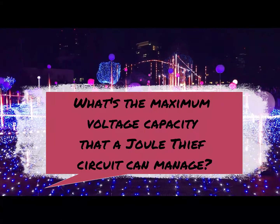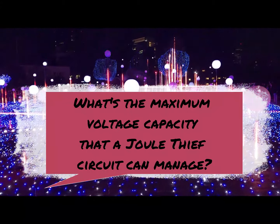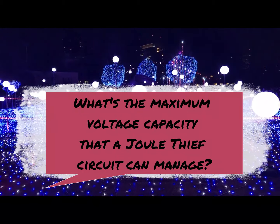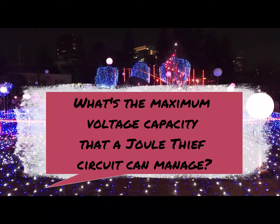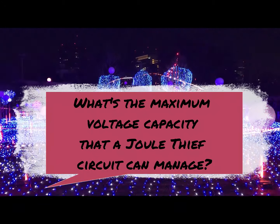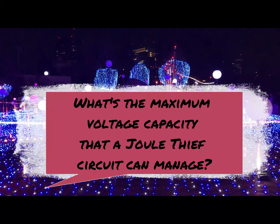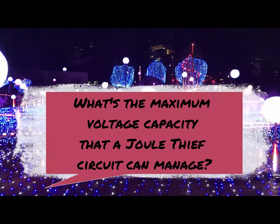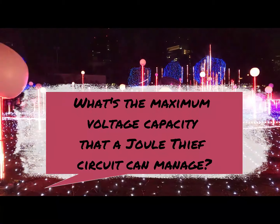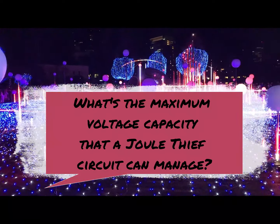What's the maximum voltage capacity that a Joule Thief circuit can manage? The maximum voltage that a Joule Thief circuit can handle depends on the specific components used in the circuit. Generally, the voltage rating of the transistor and the capacitors will determine the maximum voltage the circuit can handle. It's important to choose components that can handle the expected voltage to prevent damage or failure of the circuit. It's recommended to refer to the datasheets of the components to determine their maximum voltage ratings and to ensure they are suitable for the intended application.